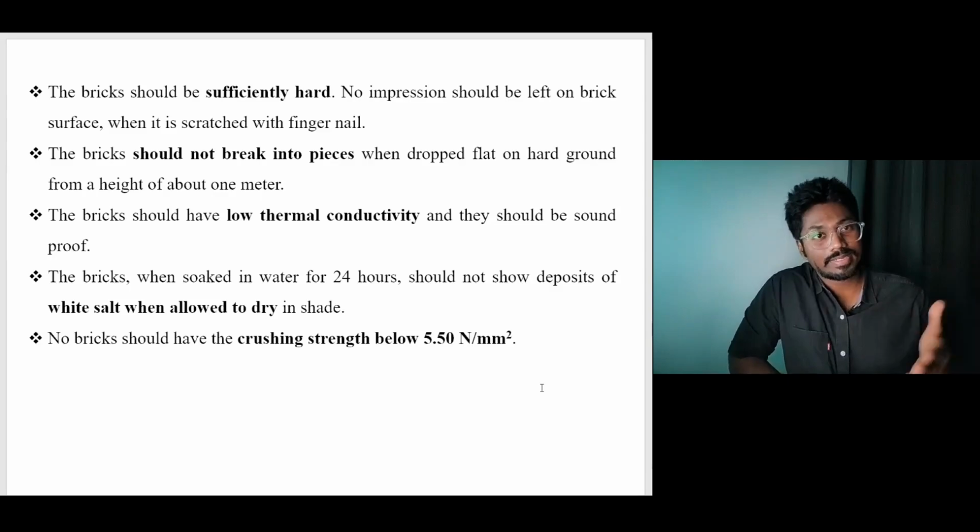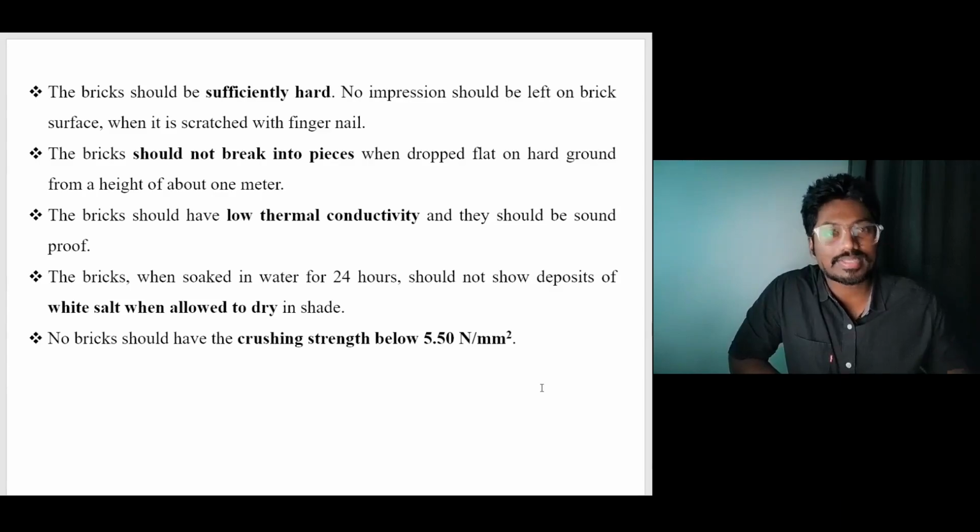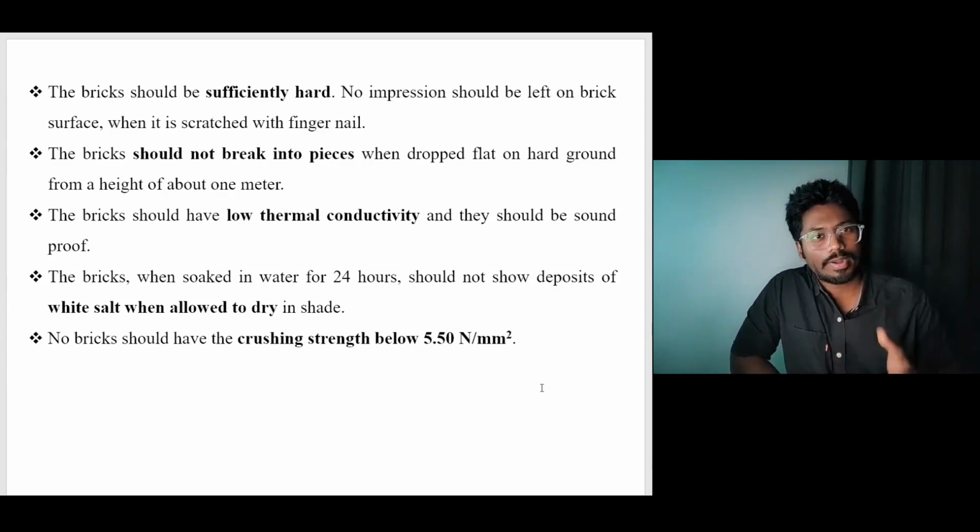The hardness index is basically based upon this particular phenomenon where you scratch a particular material with different materials of different hardness index, and this is also one test you can conduct on a good quality brick. You can call a good quality brick a sufficiently hard brick only when it doesn't show any sort of impression when you're scratching it with your nail or any hard object.